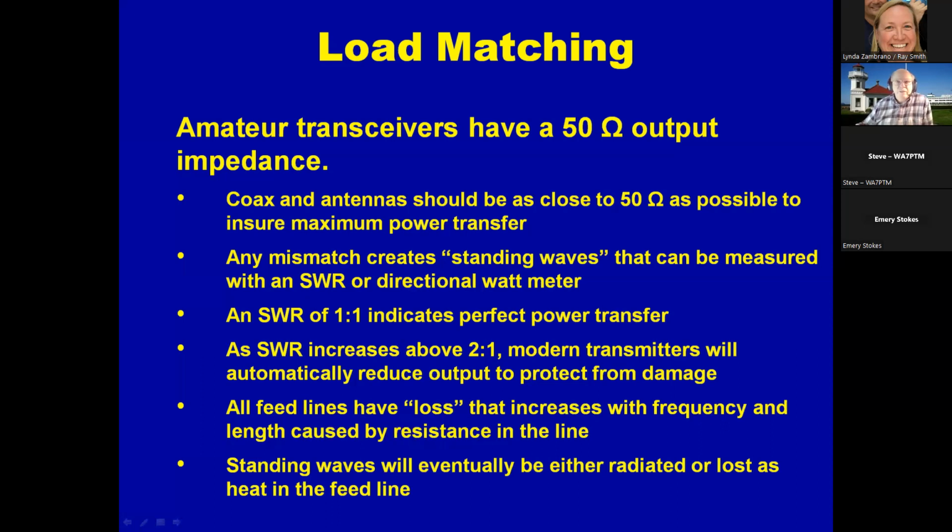As the SWR increases above 2-to-1, a lot of your radios will start to automatically throttle back the power because that energy has to go somewhere. It either gets expended as heat in your feed line, or it gets into your radio and damages your components. So a lot of the modern radios will offset that. Anything above 3-to-1, you've got to shut that down. That's going to cause damage. So that's the consideration we have with SWR, standing wave ratio.